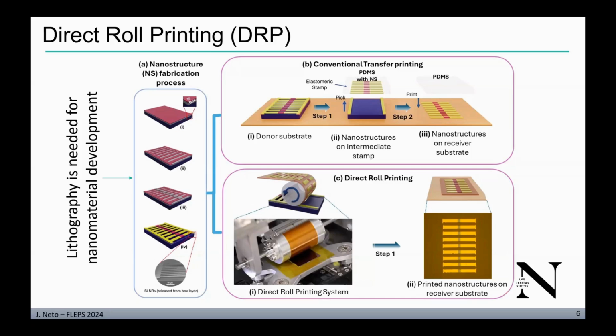Then you bring them in contact at an optimal pressure. When you apply optimal pressure, this roll will start rolling over the substrate and will pick up these ribbons. In that regard, we don't have any PDMS, so it makes the process quite simple. The registration issues that were typically associated with transfer printing, we don't have those issues. And residue and contamination issues are also taken care of. And of course, fewer fabrication steps means the overall process is much simpler and much faster.